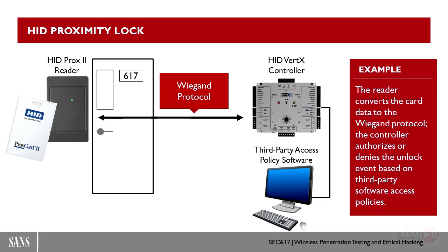As long as these controllers can speak the Wiegand protocol, they can process the data from the card to determine whether or not access should be granted, either stored locally in the database on the controller or communicating to some third-party software for larger installations and more widespread as opposed to just one door controller. Okay. So some interesting things to think about. There's at least another spot for us to attack this solution in this scenario.